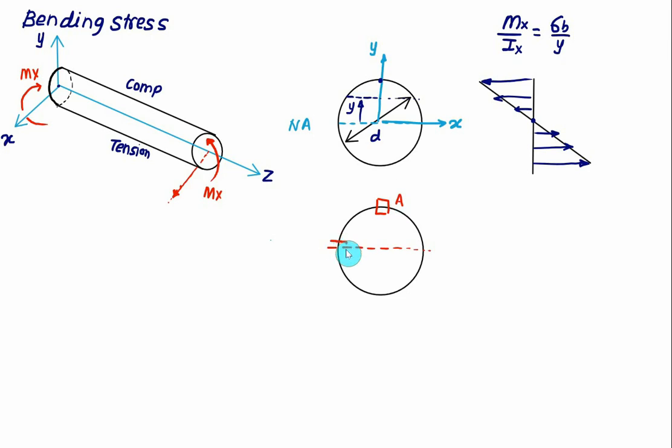state of stress on the fiber which is at the neutral axis, B and C we will consider at the neutral axis, and at point D we have the bottom fiber. So this stress corresponds to A, this stress corresponds to B and C, that is equal to 0. So the stress due to bending at a neutral axis is always equal to 0, and this stress corresponds to D. Naturally here, if I want to show the state of stress at point A, then I have compressive stress, so I will show the arrow inward.